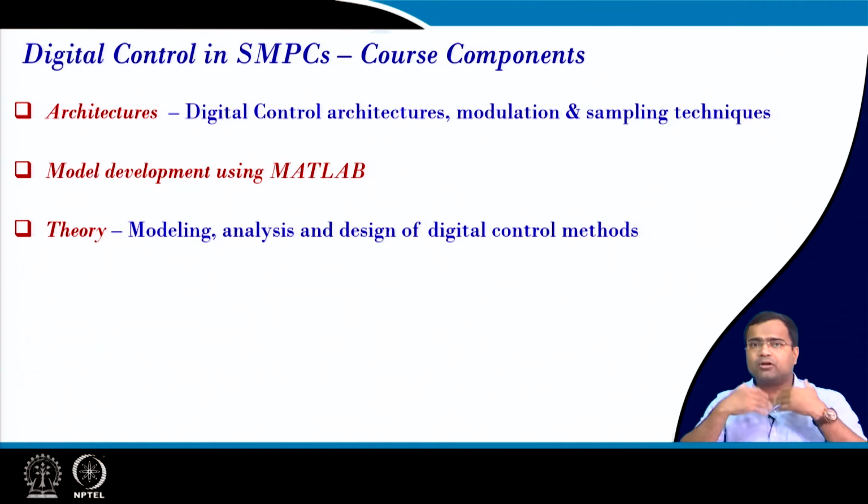So, we need to go for a fully discrete time model, but such a discrete time model may not be intuitive in terms of the pole zero concept and how they are mapped into power stage parameters, which we can very easily visualize in the continuous time model. Such a discrete time model, which has a lot of mathematical formulas and matrix exponentials, makes it hard to visualize pole zero or impedance effects, but it is very accurate.